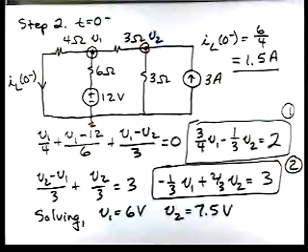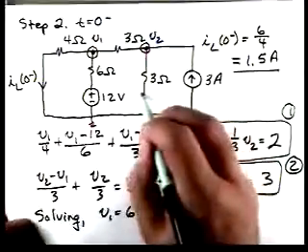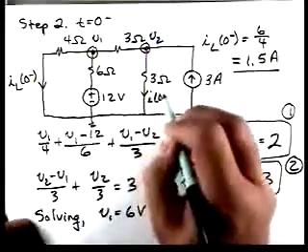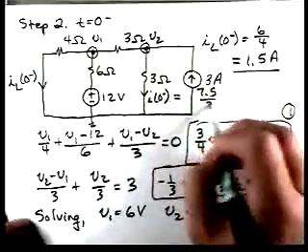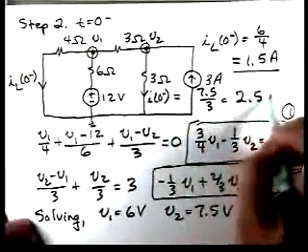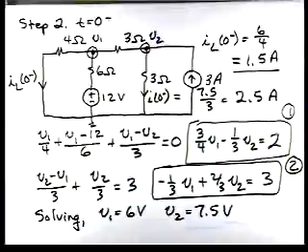And if we really wanted to, we could also solve for i0(0 minus), and that would be 7.5 over 3, or 2.5 amps. We really don't need that. We'll use it later on if we decide to plot it. But now we've solved for the initial condition on our inductor. We know, for instance, that the inductor current is continuous through the switching operation.